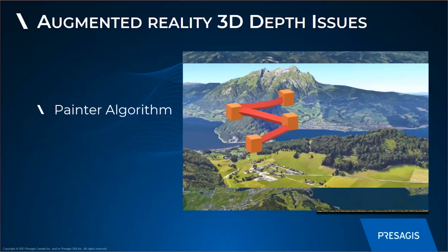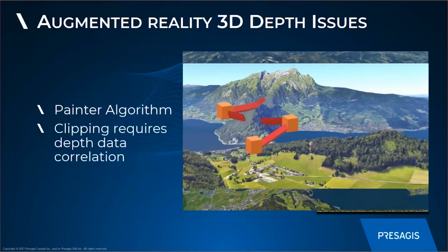However, if I come into a more shallow angle, if I move into a lower altitude and look at this situation again, if I use a painter's algorithm, I can see the same waypoints, but I'm starting to see possibly a perspective issue here. Now, it could be that my final waypoint is actually in front of the mountain. In this particular case, though, that's not the case. My actual waypoint, if we looked at our top-down view, was actually behind the mountain. So in reality, I would need to plot something like this.